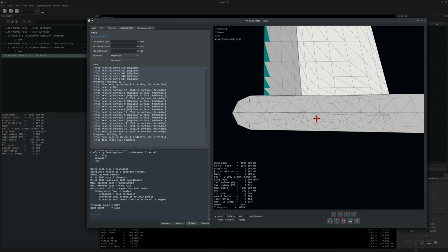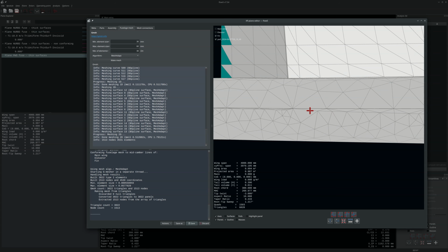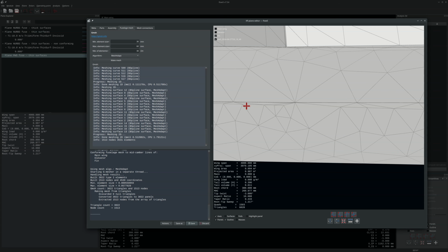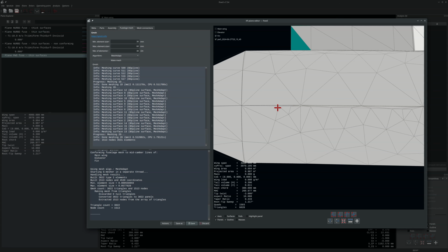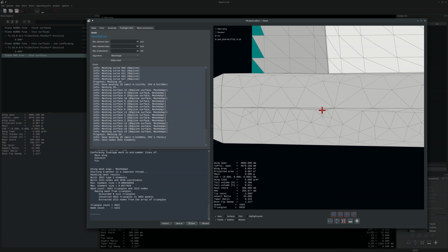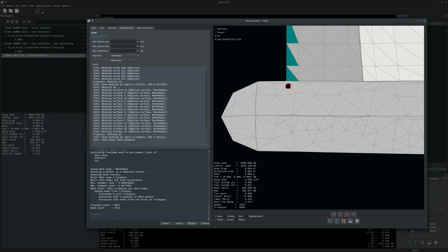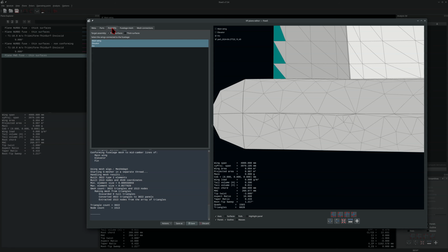However, our elevator's mid-camber line was located very close to the stitch line of the fuselage. And we can see that this mid-camber line here created very small triangles, or very stretched triangles. So Gmsh did a good job out of that, but unfortunately these are not very good triangles for the calculation. So it will still run, so I will keep them, but ideally you should try to avoid this kind of configuration. What happens if we request a thick assembly this time?